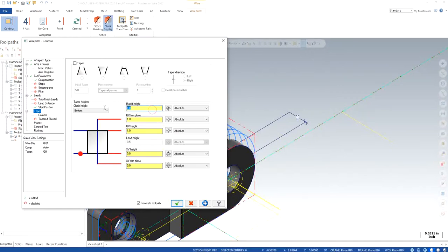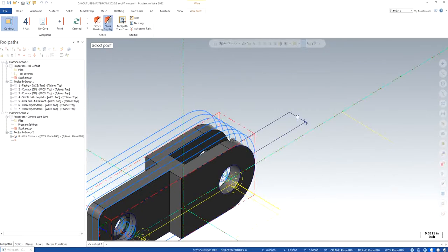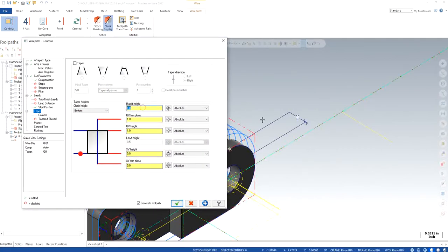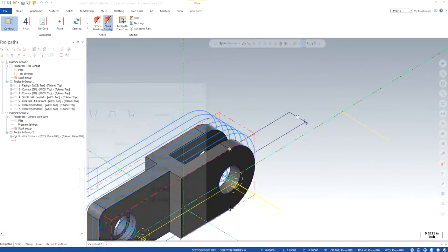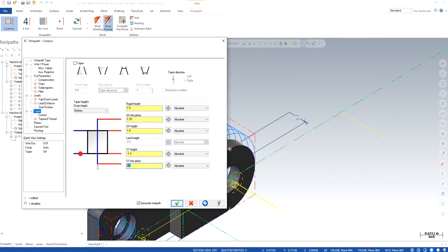So the height of it, if you're not sure, you can just simply click it and then have an estimate, or you could have done it in the bounding box option as well within the stock material. You should have done that, but if you're not sure, we can just simply click on the top. We can say the height is 1 mentioned here. We can keep 1.5. I'm just going to keep every parameter slightly above. So the height is 1. The depth, they're asking you to choose the depth right there, -1, and I'm going to give -1.25.